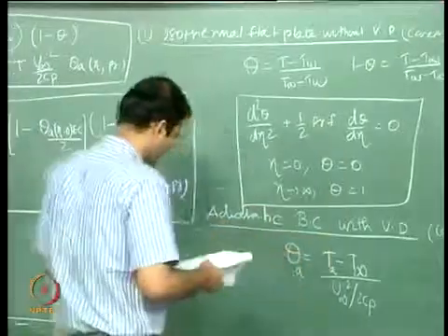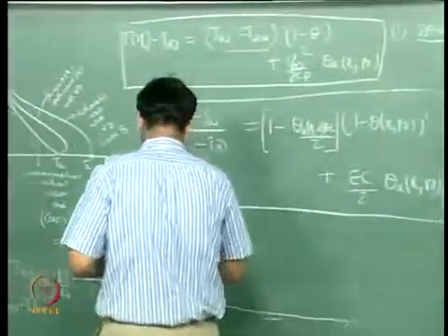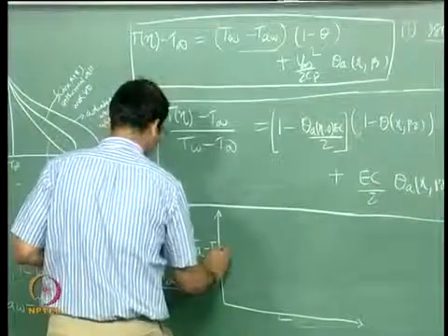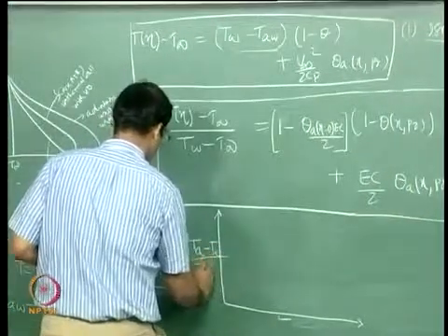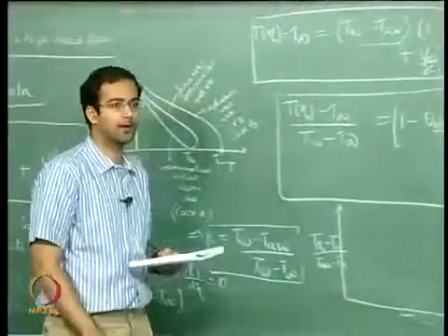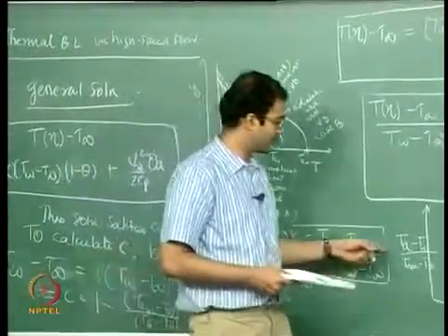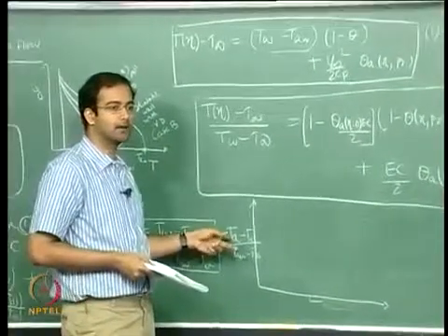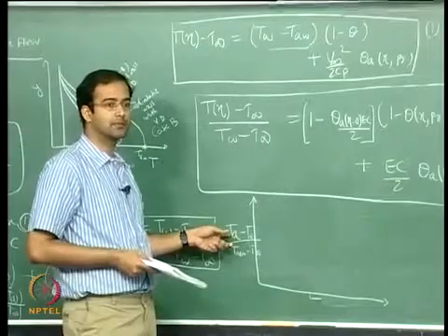Case B, if you plot it, non-dimensionalize the adiabatic temperature as Ta minus T infinity by Ta wall minus T infinity, such that it scales between 0 and 1. So at y equal to 0 this becomes T adiabatic wall, it becomes 1. At y going to infinity this becomes 0.